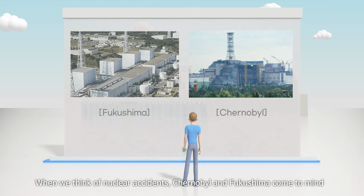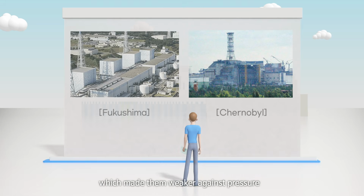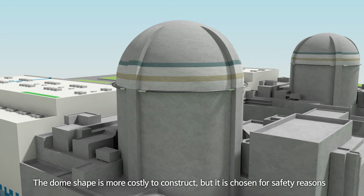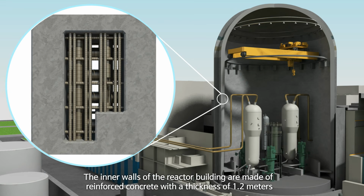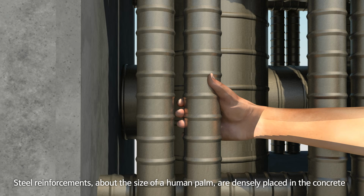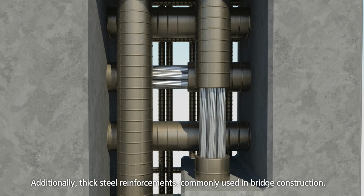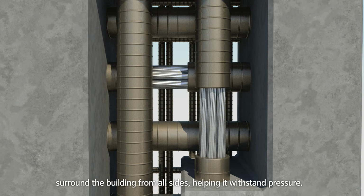When we think of nuclear accidents, Chernobyl and Fukushima come to mind. Both were not dome-shaped but had a shape of a square, which made them weaker against pressure. The dome shape is more costly to construct, but it is chosen for safety reasons. The inner walls of the reactor building are made of reinforced concrete with a thickness of 1.2 meters. Steel reinforcements about the size of a human palm are densely placed in the concrete. Additionally, thick steel reinforcements, commonly used in bridge construction, surround the building from all sides, helping it withstand pressure.